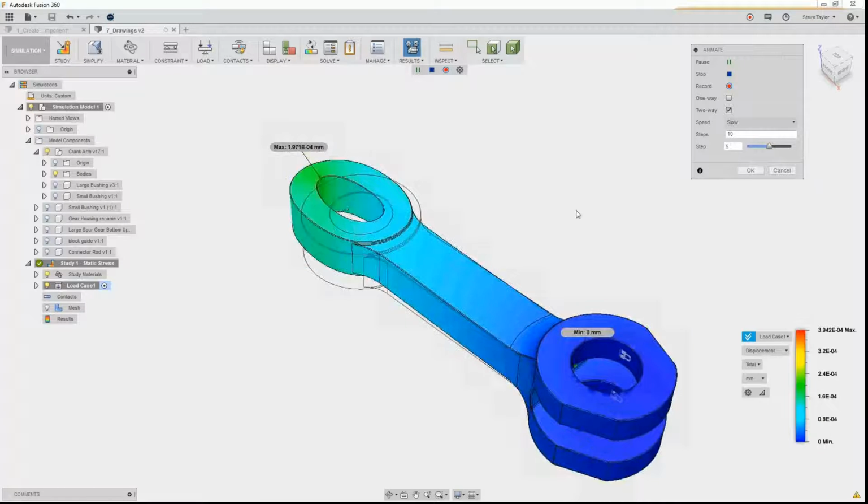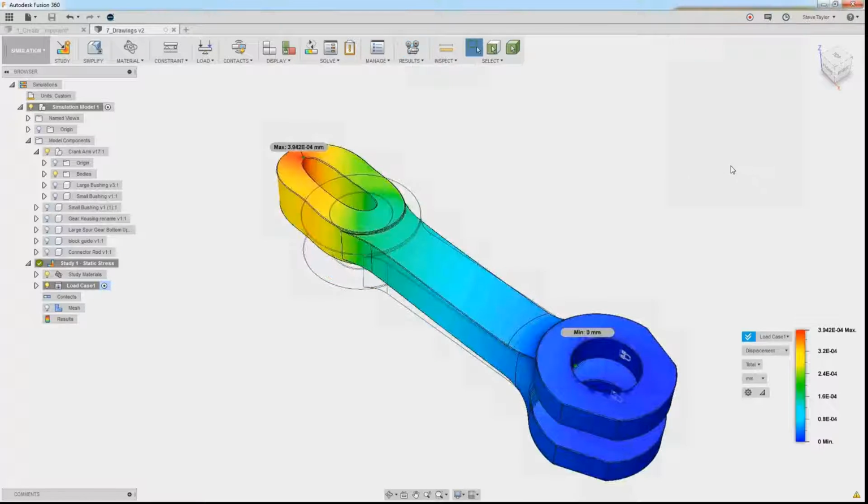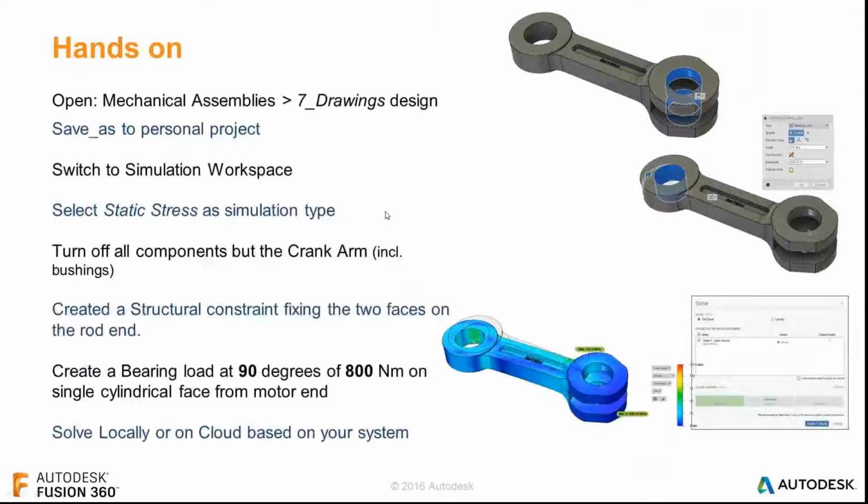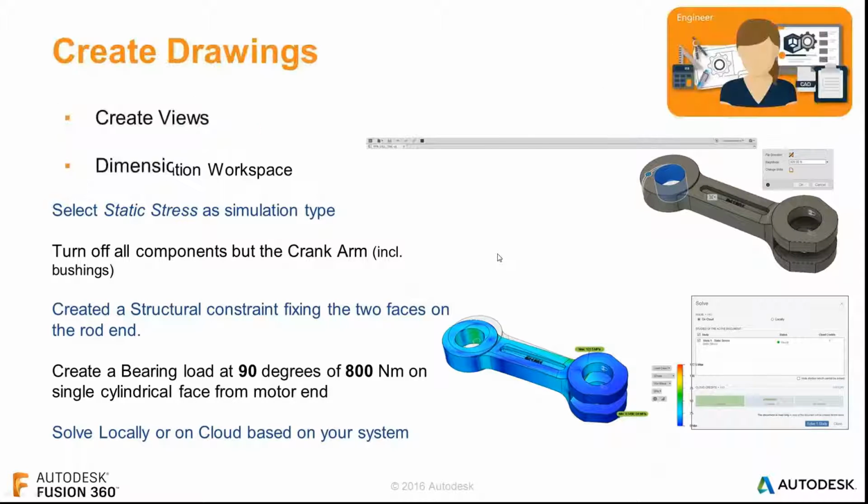And if I cancel that now, if I just OK, you've got the ability to rerun the study with a different material. So you can just rerun the study on the same component using a different material, which is quite good because you then have a good comparison between the two. We go back to now. So we've done a little bit on demonstration. It shows us a little bit of what we can do there. On our PowerPoint, which you'll have a copy of, it'll give you an idea of things that you can test and how to use it.